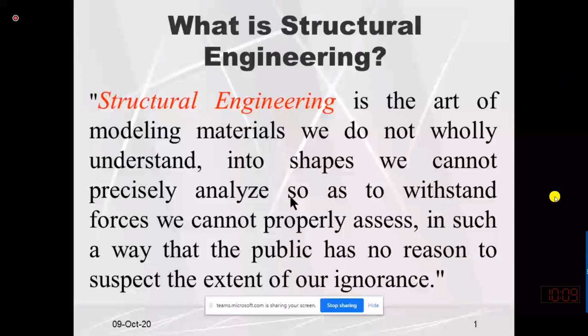When we are computing the load, there are a lot of approximations. For example, say this is a structure made of maybe a steel building or a concrete building. I assume the self weight. Before designing, I cannot actually estimate the load, so I assume that the self weight will be 10% of the total load. Again, there is approximation in my assumption.